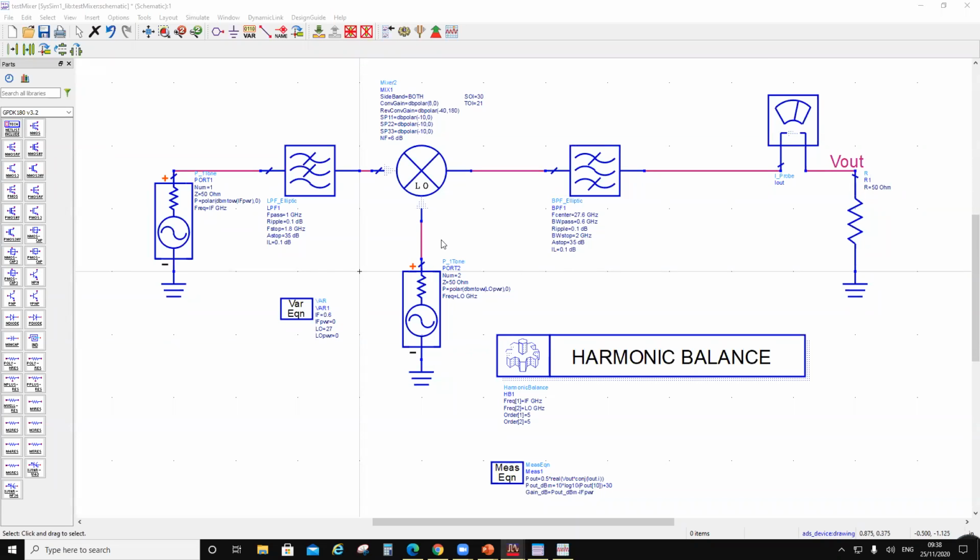Okay, so yesterday we left it at this point that when we put this filter there, there's a lot of issue. Actually, there should not be an issue when you put a filter there. The problem is this reverse conversion gain. This reverse conversion gain should be a very small number. That was the major problem. If I was putting here -10 or something, that's a problem. So I increased it up to -40. So now everything makes sense.